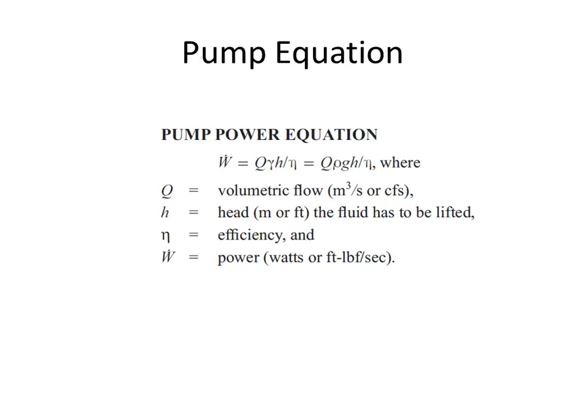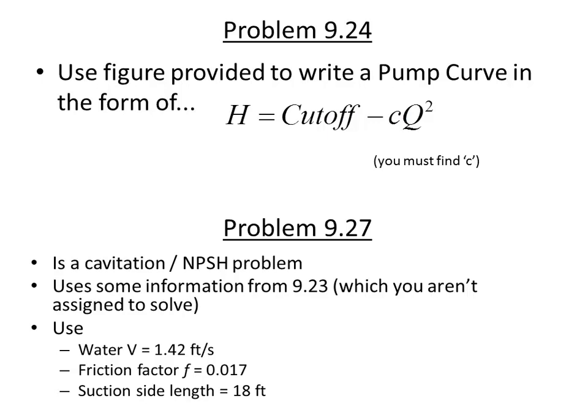This is talking about the pump power that's going to be used to move water from place to place. And so you'll notice they're dividing by the efficiency. If you've got a pump that is not 100% efficient, remember you're going to have to distinguish between the energy or the power that's going into the pump and the power that's applied to the water. I just wanted to point out that the equation in the equation packet looks a little bit different than we've seen it.